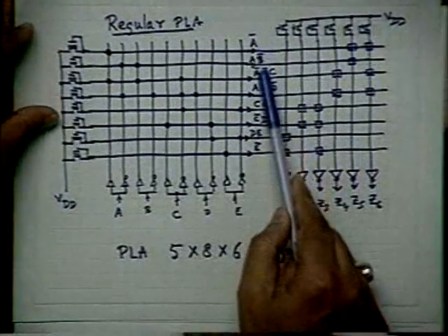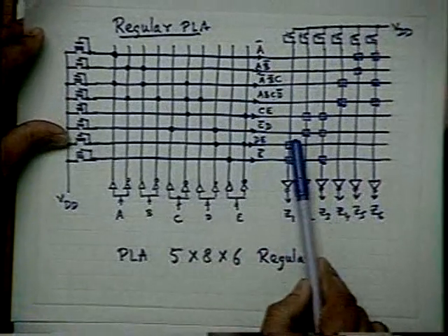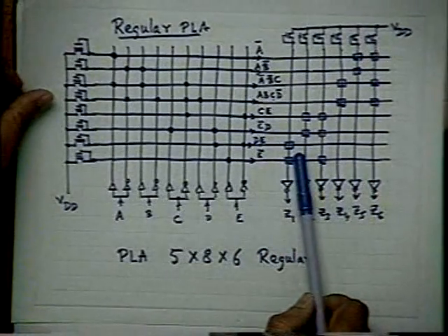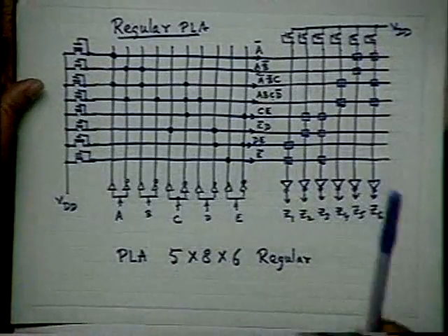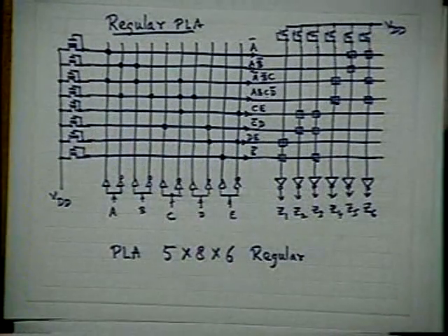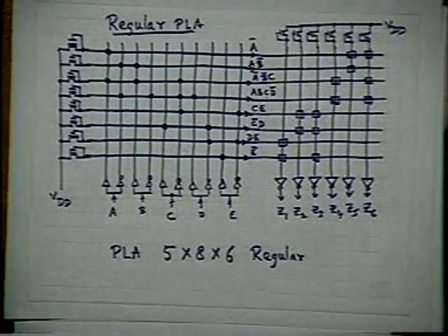Now, if you are interested in row folding, you first organize these product terms in such a fashion that A, B, C, D, E are most separated from each other. I first consider whether there is A or not. I first see whether any term is there which involves A only. I keep its position at the beginning, in the first.